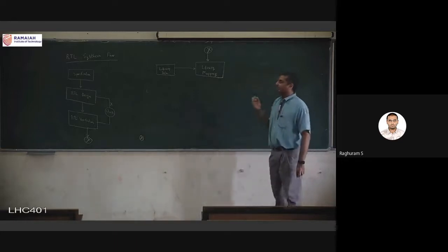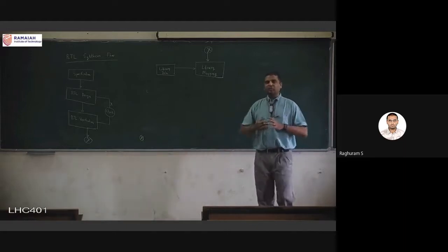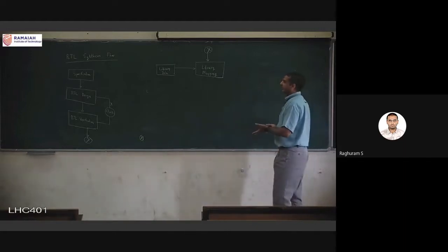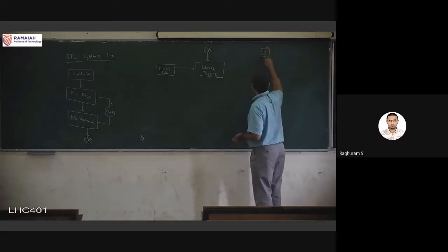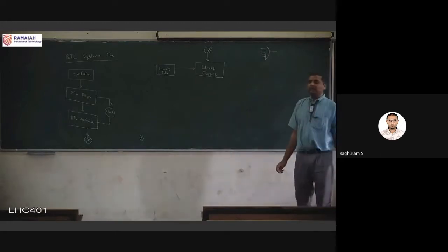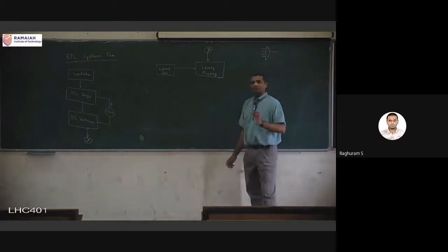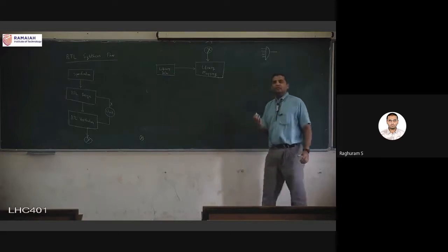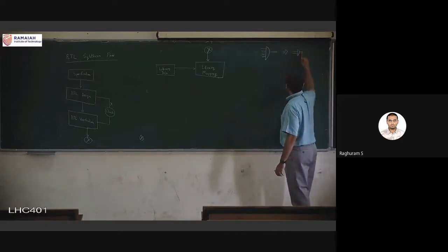Okay, this library is very important for us because we don't have access to all sorts of gates. So for example, the gate level netlist might have produced something like a 5 input AND gate, okay? But a 5 input AND gate might not be part of my library, and I want to produce a design that only consists of gates or cells, both are the same, from my library. So we have to produce that transformation. So for example, this might be a very simple conversion.